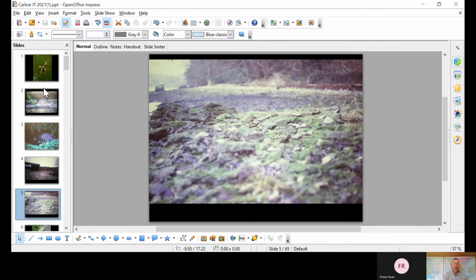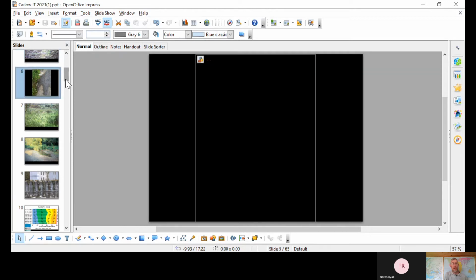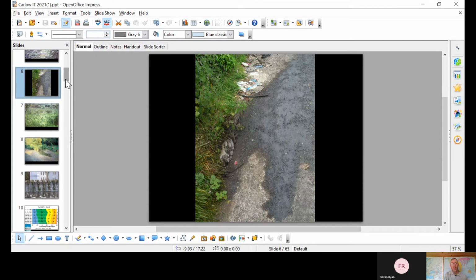And as I say, when you get into the sea, the phosphorus won't be a limiting factor, but nitrogen will. So nitrogen from sewage or from industry or from agriculture will all contribute to the general levels of enrichment within the sea. And you can see the green algae there growing on the water in Cork Harbour. That's the result then. So nitrates, phosphates, microbial pollution, so pathogens, that's another issue. BOD, suspended solids, those are all issues. Another thing to bear in mind with water is just hydrocarbons and general stormwater pollution coming in from roads. You can see here an oil spill on a small back road. And so those are the main pollution inputs that we have around the country.